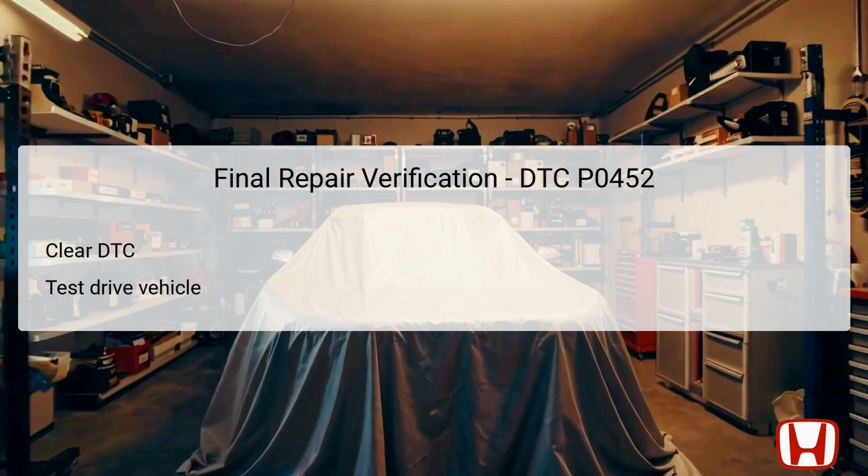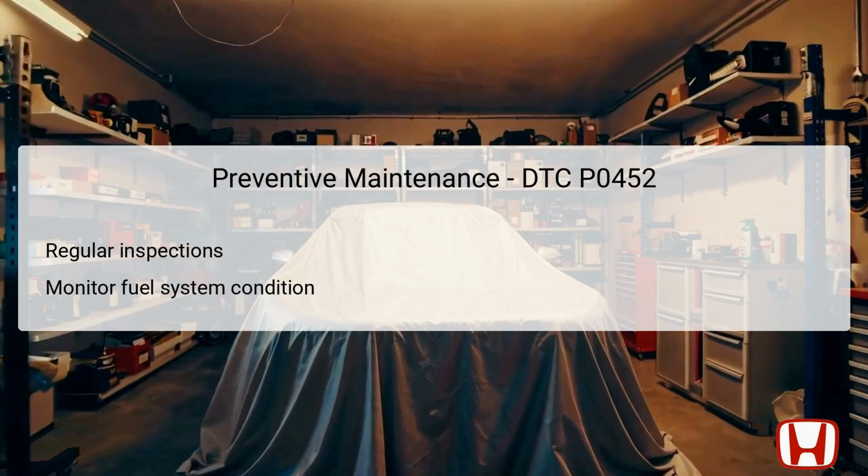Preventive maintenance plays a vital role in reducing the risk of experiencing DTC P0452 in the future. Regular inspections of the EVAP system, including the FTP sensor and its associated wiring, can help identify potential issues before they result in a failure. Additionally, monitoring the overall condition of the fuel system is essential.